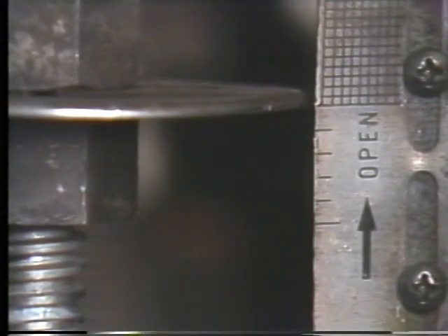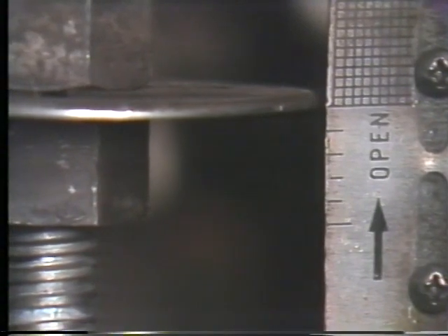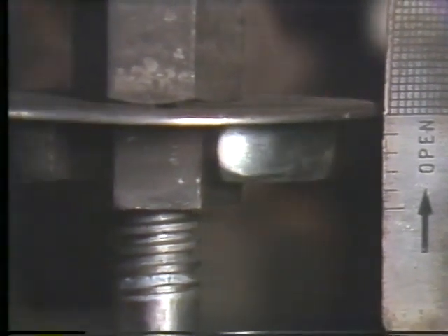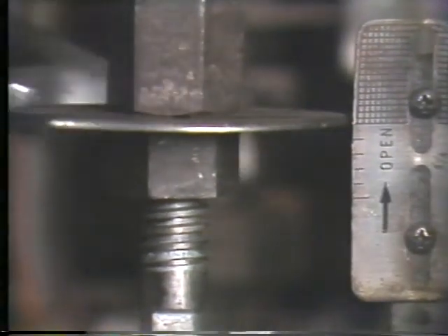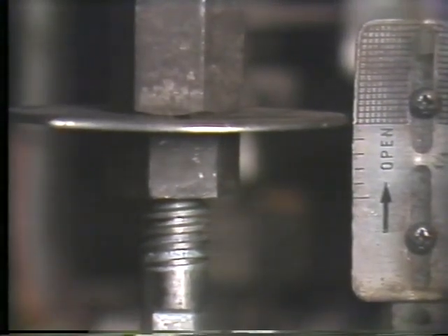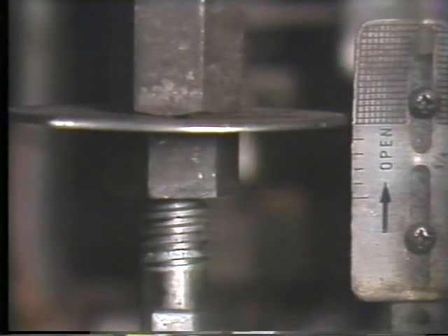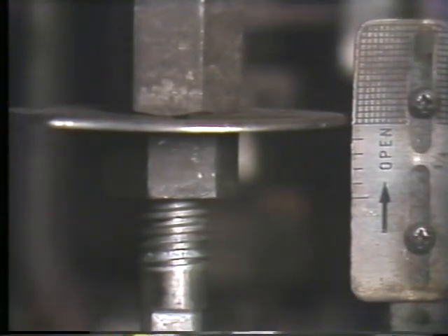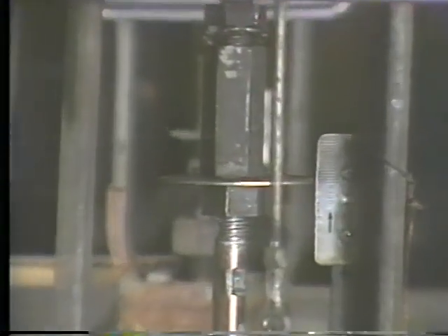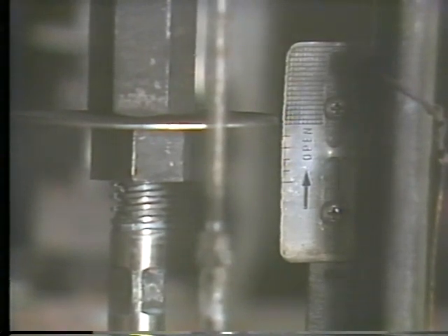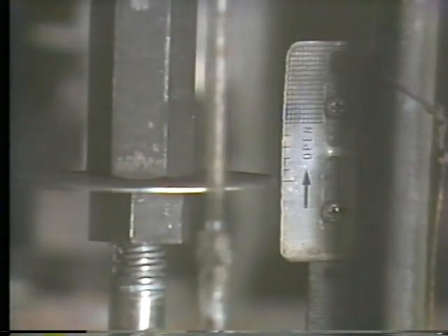After the valve has been raised so that the indicator plate on the valve stem is lined up across from the high mark on the travel indicator scale, tighten the two hex nuts together. Once the two nuts are tightly secured, we can release the air pressure that is holding the actuator diaphragm up so that the actuator stem, valve stem, and valve can be lowered to the closed position. In the closed position, the indicator plate should indicate the lowest or closed position on the indicator scale.